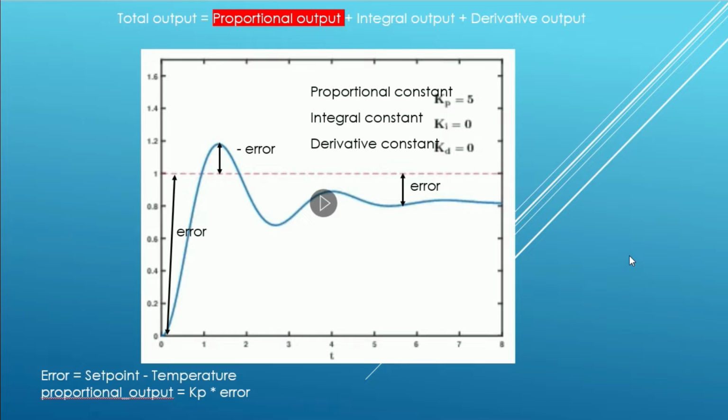If this was a temperature control system, then the set point would be the thermostat control. The control variable would be the temperature sensor feedback, and the control output would be the heater control. With a large error, the heater control would need to be turned on aggressively, like at 100%. And then the turn-on percentage would be decreased as the control variable gets closer to the set point.